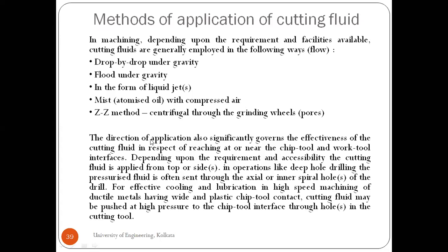Now, the direction of application also significantly governs the effectiveness of the cutting fluid in reaching at or near the chip tool and work tool interfaces. As I told you, the chip tool interface is a secondary zone where the maximum amount of heat is generated.